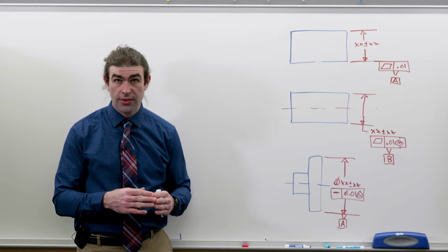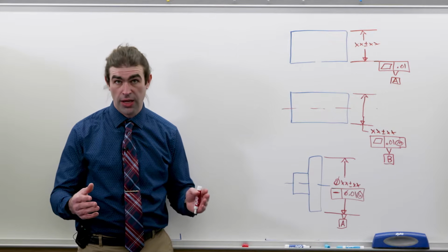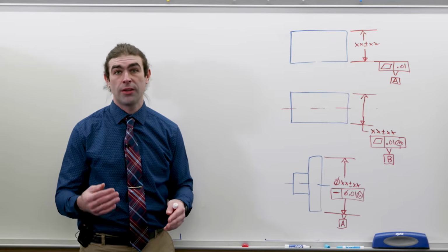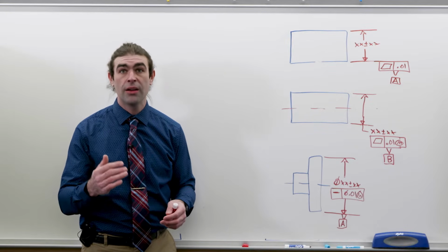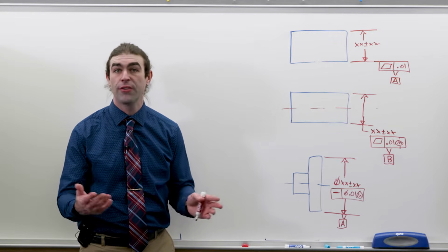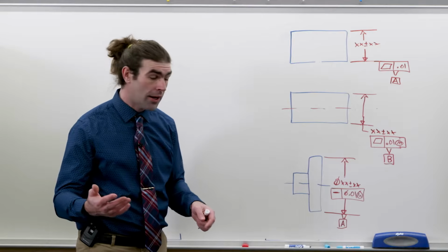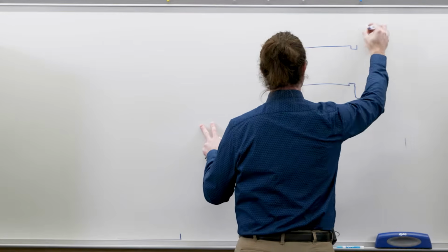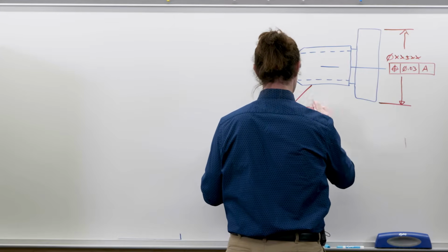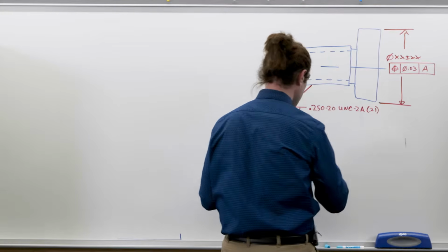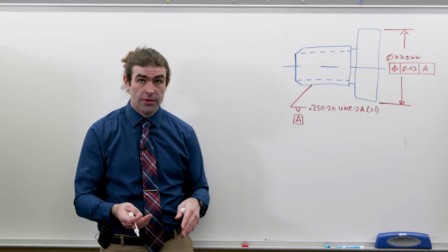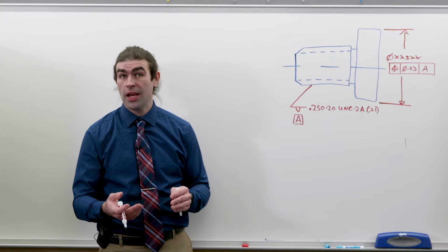The planes and cylinders are the most common. Most parts you can get away with either a surface plane, center plane, or the axis of an internal or external cylinder for a lot of your datums. But it's also somewhat common to see threads called out as datum features.